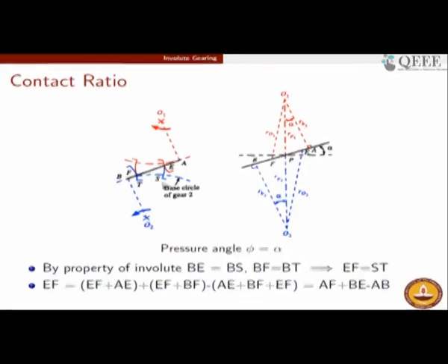The following tooth pair will come into engagement at some duration of time later. So there is an interim duration where there is no engagement happening between the two gear tooth pairs, and as a result the concept of positive drive is lost within this interim time period. That is definitely not advisable, because in that interim time period the mechanism will be moving only because of its inertia. It is not going to move because of one link pushing the other.